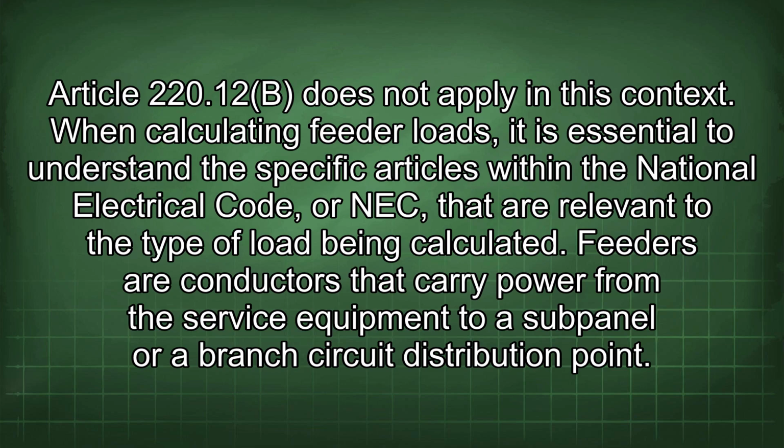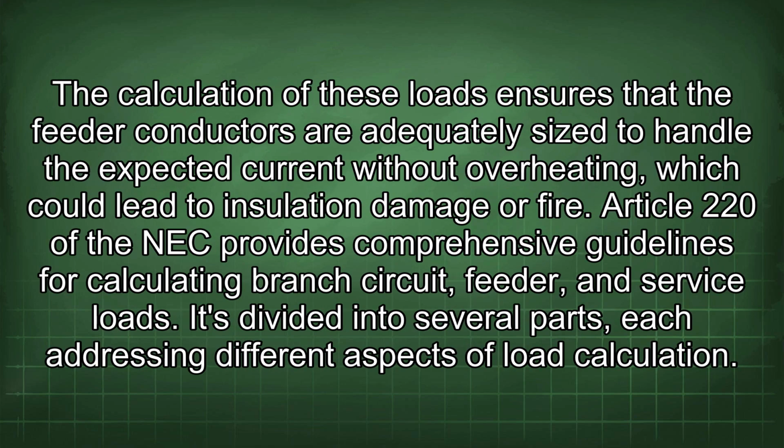When calculating feeder loads, it is essential to understand the specific articles within the National Electrical Code, or NEC, that are relevant to the type of load being calculated. Feeders are conductors that carry power from the service equipment to a subpanel or a branch circuit distribution point. The calculation of these loads ensures that the feeder conductors are adequately sized to handle the expected current without overheating, which could lead to insulation damage or fire.